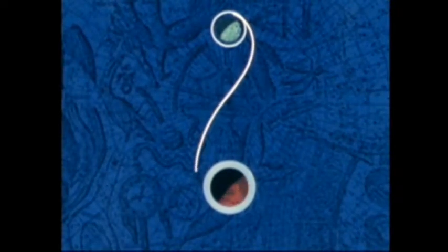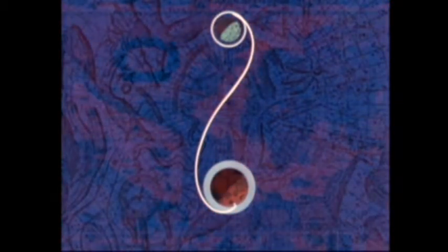By selecting the proper trajectory, we can vary the transit time of the spacecraft up to 24 hours. In order to bring the spacecraft to the longitude of the recovery forces, it is only necessary to control the return time of the spacecraft to the Earth, while the Earth rotates into the proper position. This gives us complete freedom of choice as to selection of the landing longitude. The landing longitude, then, can be selected with operational constraints in mind, such as a required landing on water, location of land masses, convenience of recovery force placement, and so forth.